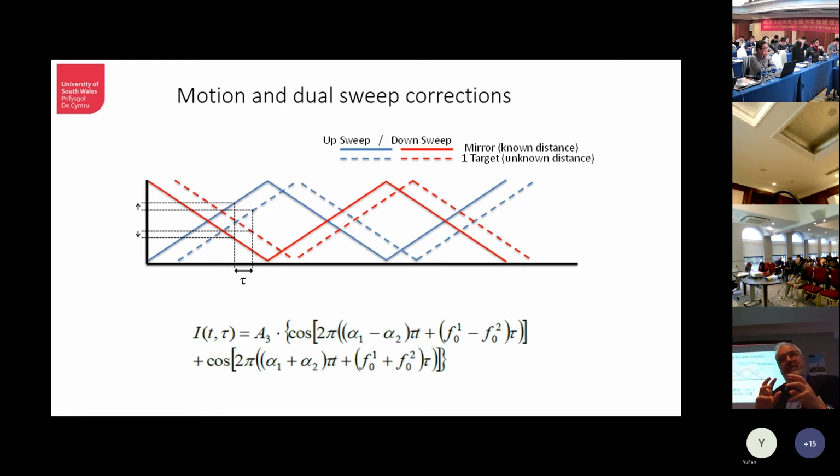When you multiply the outputs from the two together, which you do electrically, very similar to doing the sum and difference using second harmonic generation, using a nonlinear process, which in this case is a detector because it gives you a signal proportional to E squared, you separate those frequency terms out. You separate the vibration, assuming it's sinusoidal, from the actual beat frequency generated by the chirp, so you get the sum and difference of these frequencies coming through.